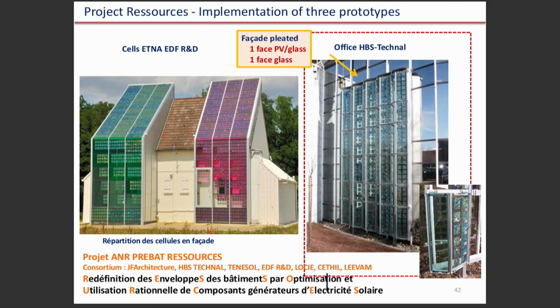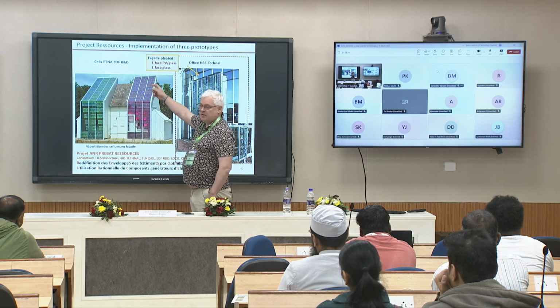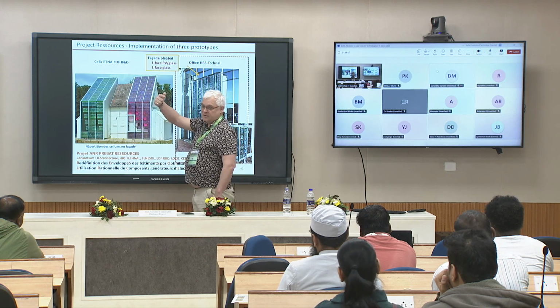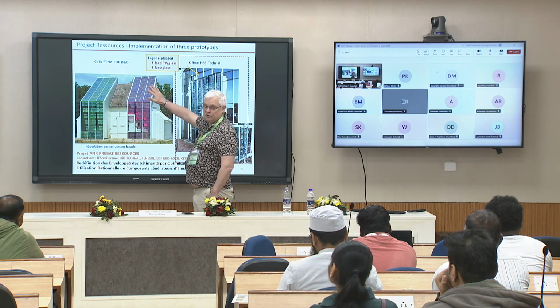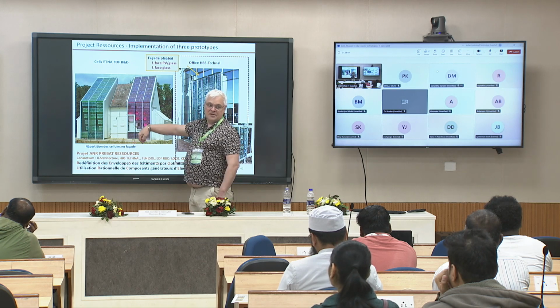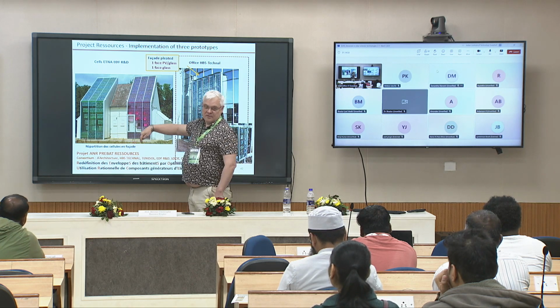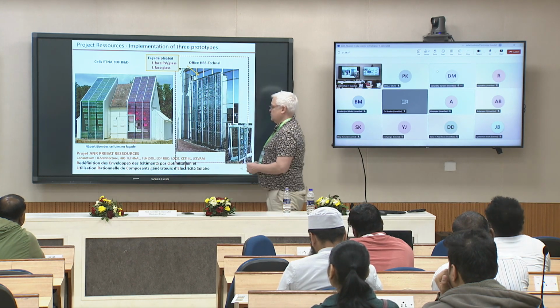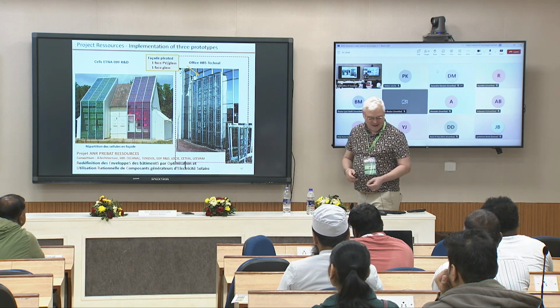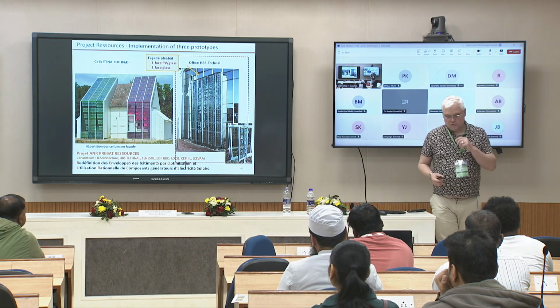Of course we have to be sure, especially here, that there is no local dominant wind in the other direction, because everything you are expecting from natural ventilation due to the chimney effect could be completely neutralized by a dominant wind that will come and blow inside. It was not the case, hopefully, and so we made some experimentation to look at it.